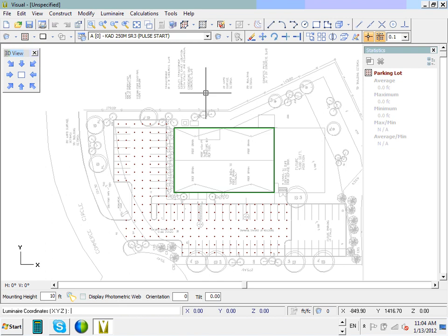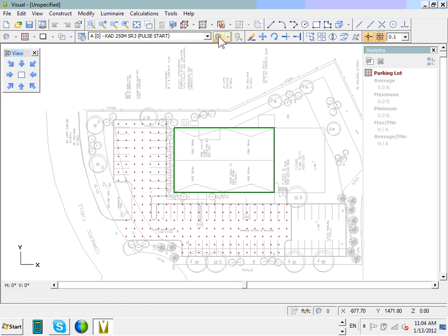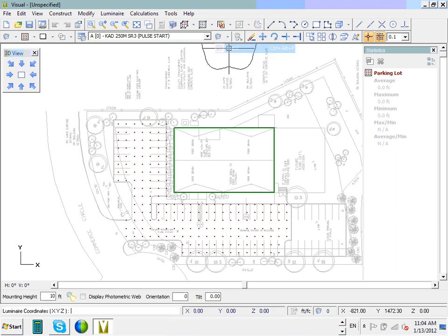Do you guys, one more time, click it from here. Do you guys see why it's important to do the contour? Now that line here is what it shows you. The line shows you the minimum. So that's the minimum, the line. One more time, escape, click here, place on face. Okay, now, did you guys get it?